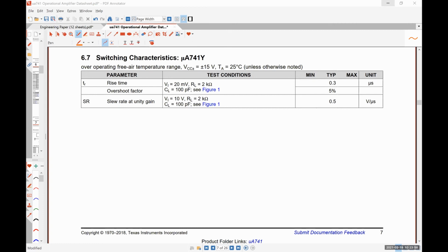The internal capacitances are too large for our amplifier to accurately process the information it's being fed. So that's a fundamental difference between gain bandwidth product and slew rate. They're both due to the internal capacitances, but the effects they provide are different.